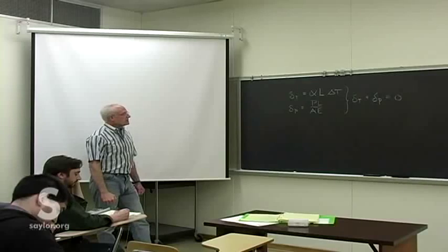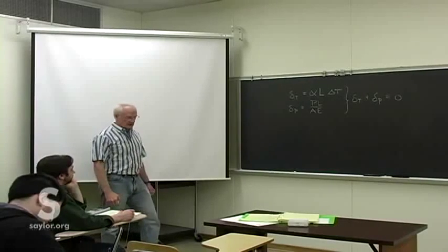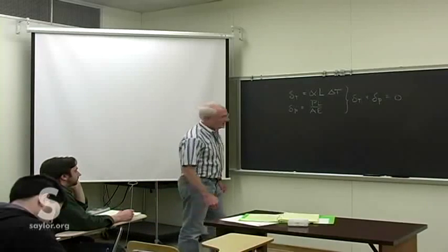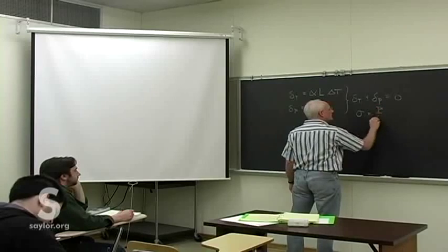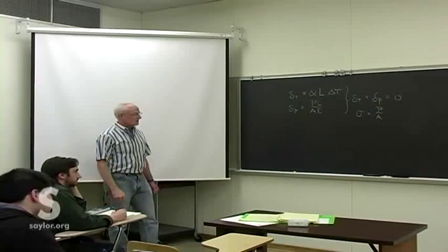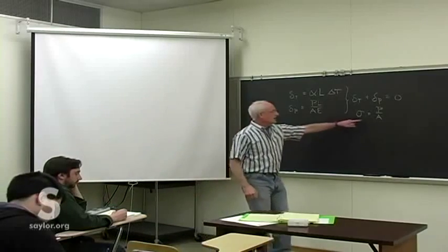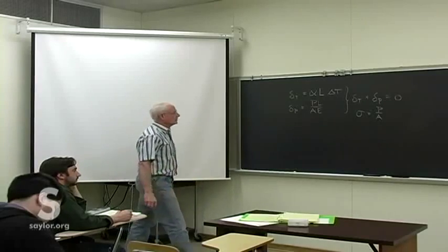So, given the change in temperature, the thermal expansion, the other material properties, we can figure all this out, and from that we get the stress. And remember, when we were calculating stress, it was always per original area, so the fact that this expands radially is not of great concern.